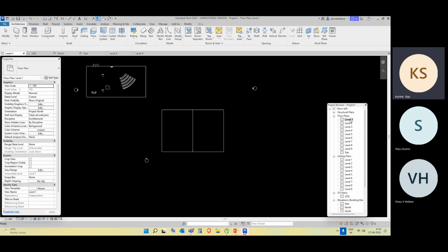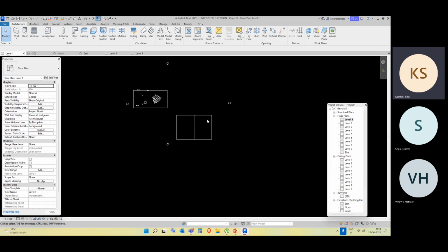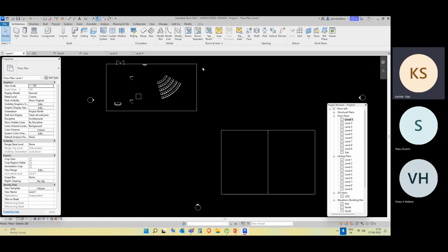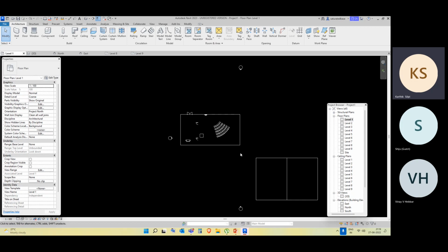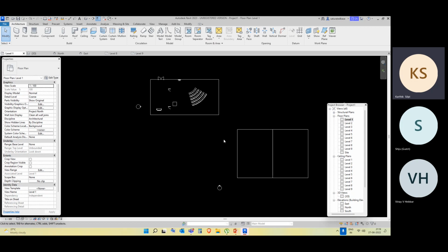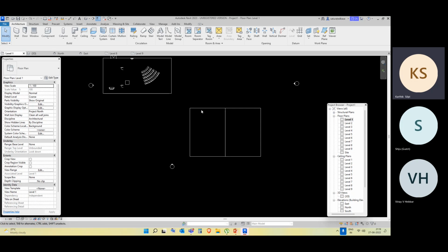This is especially useful when you're drawing floor plans and in the washrooms or toilets, WC area. If you're drawing floor plans, make sure that you provide the slope, that's it. Because the MEP guys also provide floor drains and all, but in the architectural drawings, you have to just provide the slope for the floors.